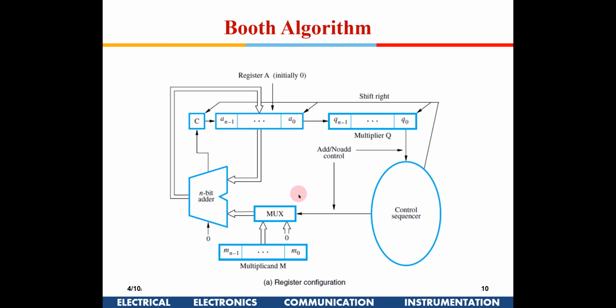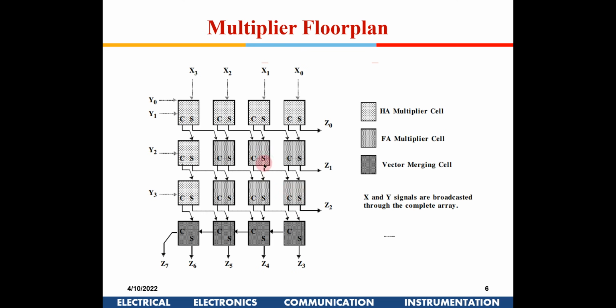Whereas here, each block might have a few picosecond delays, and just tens of, maybe less than 10 nanoseconds of delay, but that is a trade-off which you have to look at: how much area and power. Generally, the trade-off in VLSI design will always be between area, power, and delay.